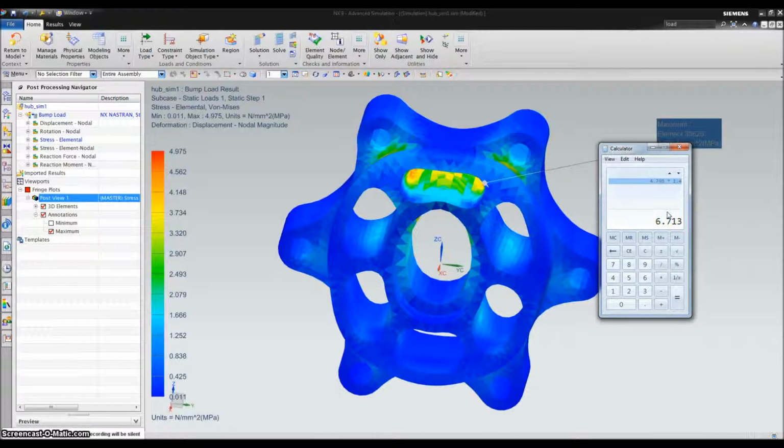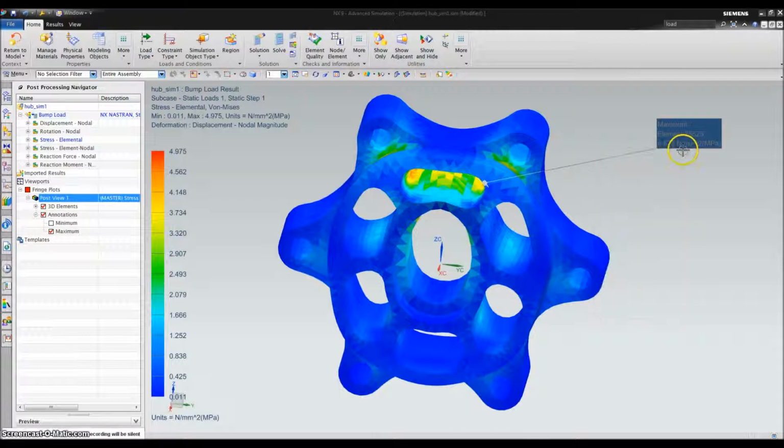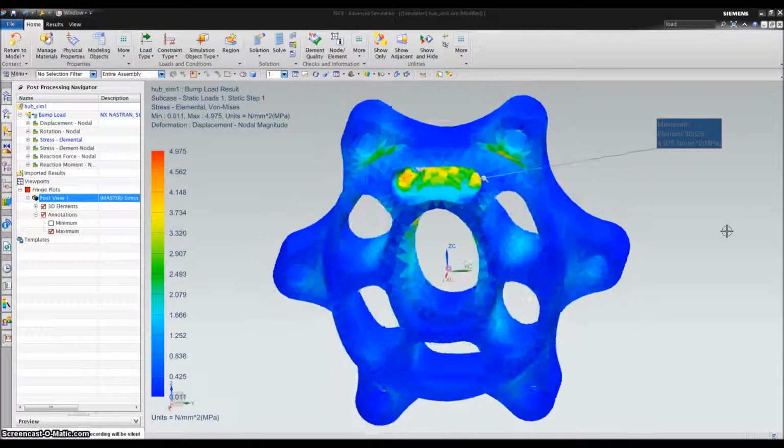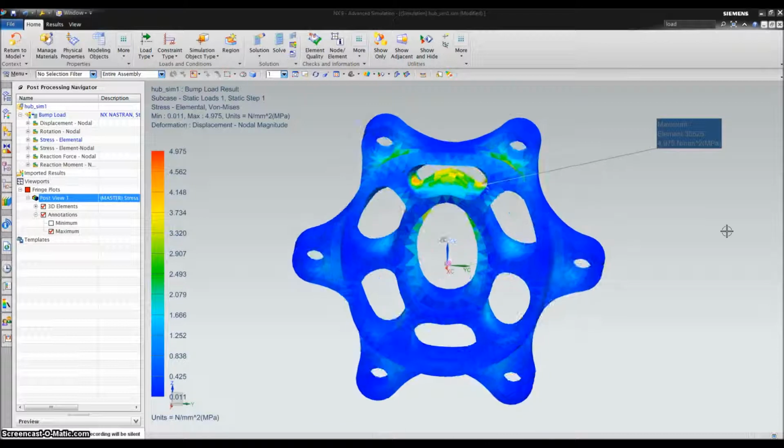And then I say, okay, 4.975 times 2, my factor of safety for ultimate tensile strength, that's 9.95, and I can check the ultimate tensile strength, and I can say, okay, is the ultimate tensile strength any less than 9.95? If the answer is yes, then I have a problem. We like to be extra safe on this team, and those are good standards to abide by. Factors of safety of 1.4 for yield and 2.0 for ultimate.